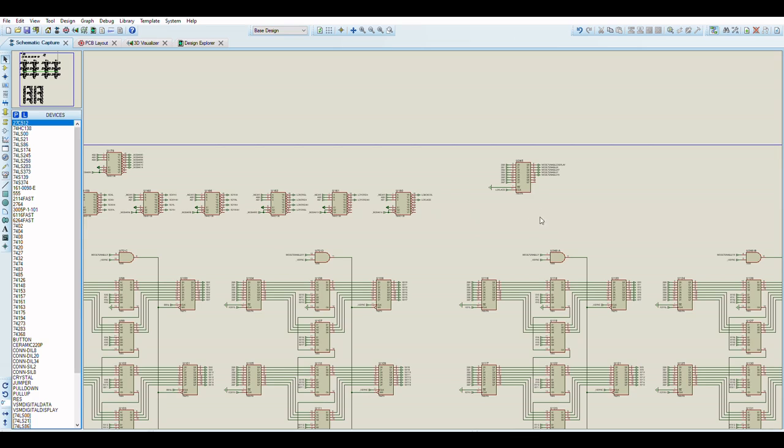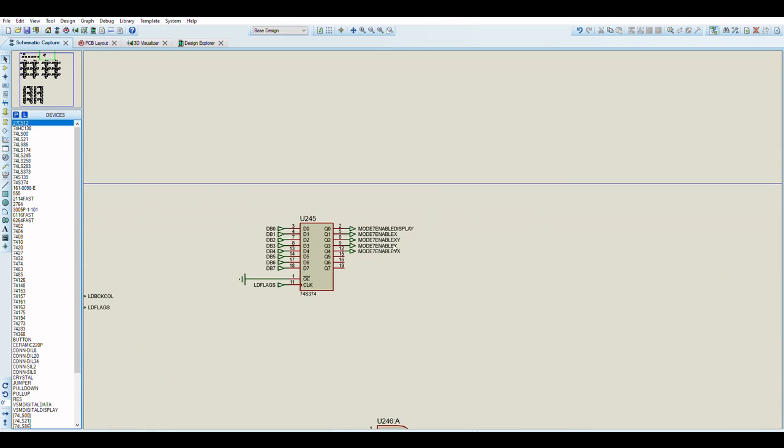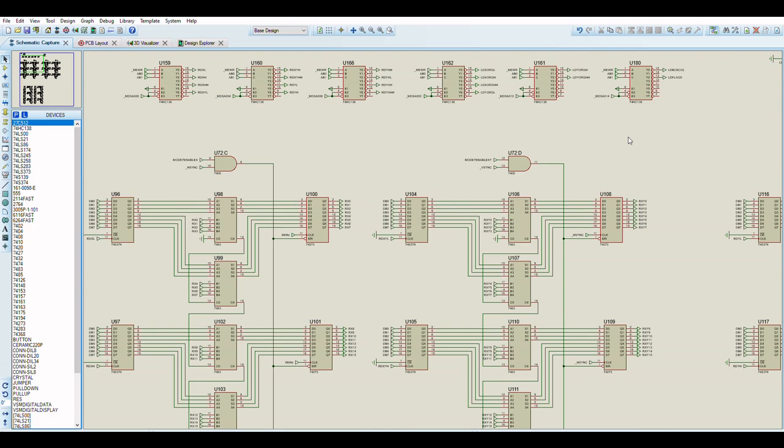There is also a last control register which decides on whether or not the Mode 7 layer is displaying anything at all, and whether or not the internal counters for X, XY, Y, and YX are held at 0, or if they are allowed to accumulate values internally. Mode 7 layer allows transformation, rotation, scaling, shearing, and flipping.